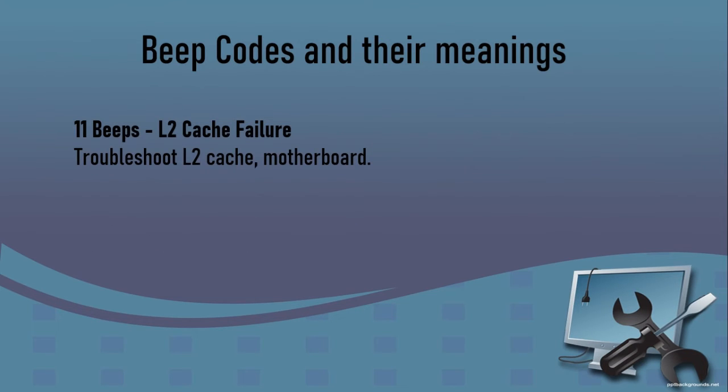11 beeps. L2 cache failure. Troubleshoot L2 cache, motherboard. This usually means a problem with the system cache. It may also be a more general problem with the motherboard.